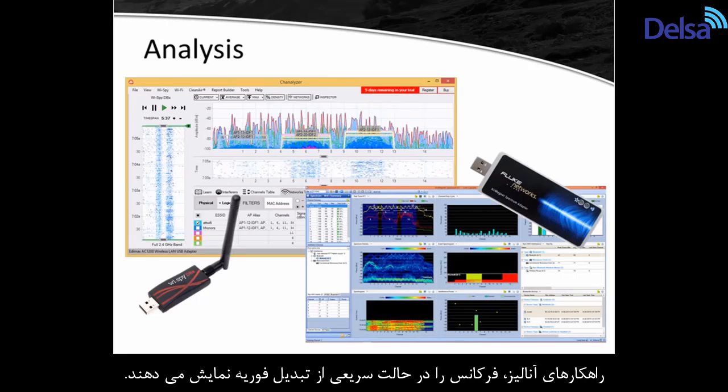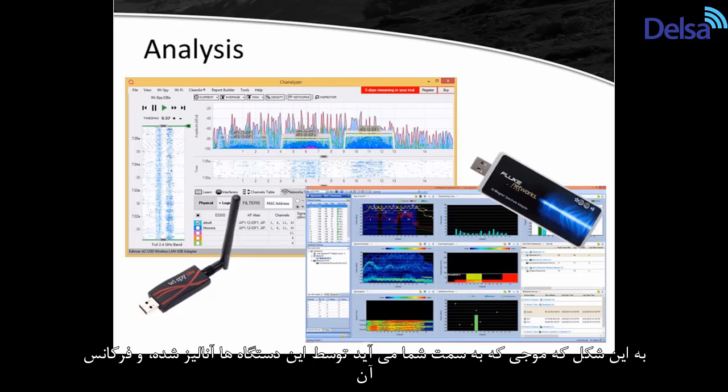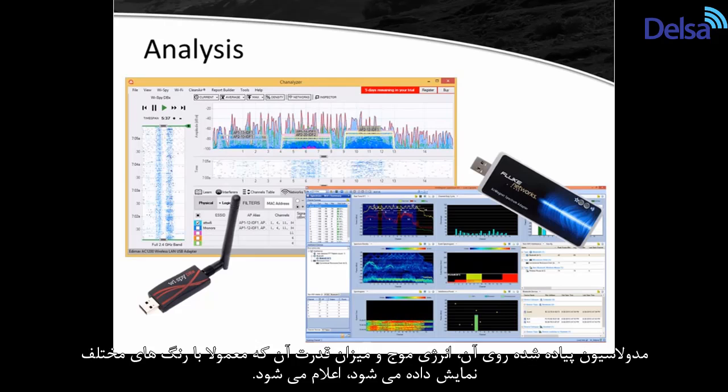So what they'll do is they'll show you the frequencies in fast Fourier transform mode, which is where I like to say it like this: think of it as if the waveform is coming right at you and you're looking at the individual frequencies and what's being modulated on them. And then you can also see things like swept spectrogram and these types of views that are going to show you the RF energy over time in visual representations, usually using color to represent the strength of the signal.